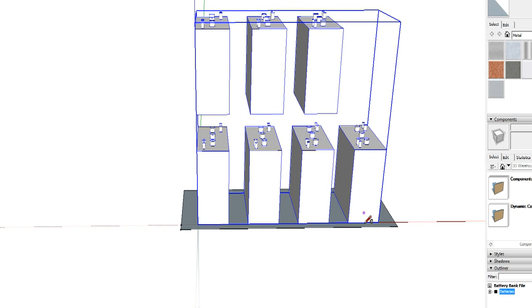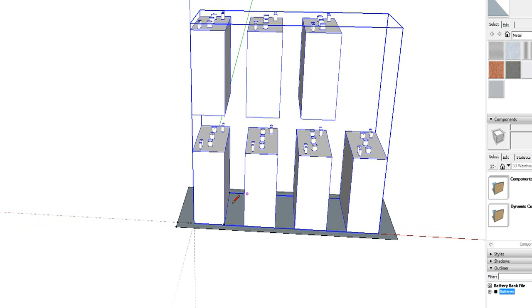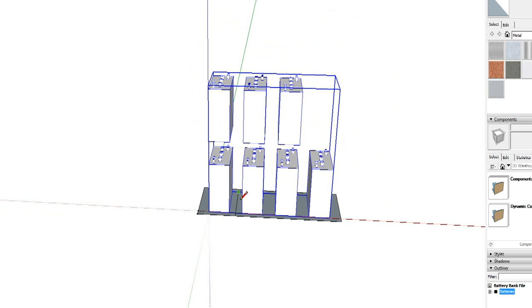Now I want to put my holes in. I want a brace in between all the batteries and on down the edge. So what I'm going to do to achieve this is select my line tool, and create some reference lines as I did before when we created the battery. Your line tool is L, and when you create a line, it says it's going to connect another line to it. To break that and keep the line tool open, you simply press L again. And then a midpoint to midpoint, and one last one.